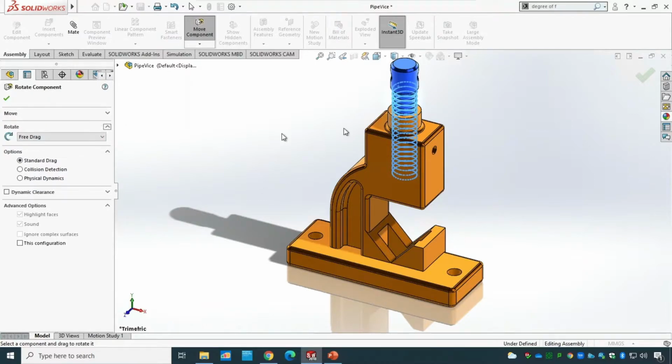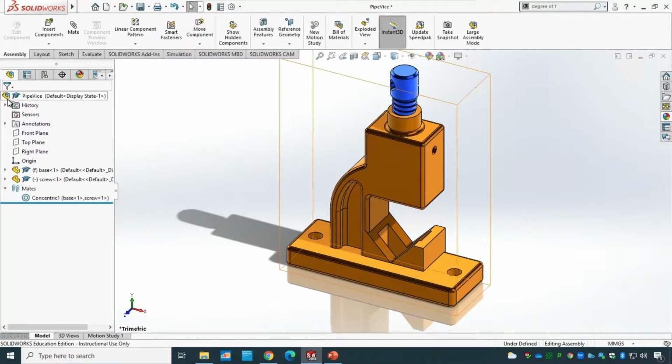And of course, you would be able to rotate freely as well, because there is no degree of freedom for the rotation right now. And I'm gonna click OK. So what we've done, we already talked about the mate relation. We already talked about how you can modify the parts. Also, we talked about how we would be able to move or rotate them around.